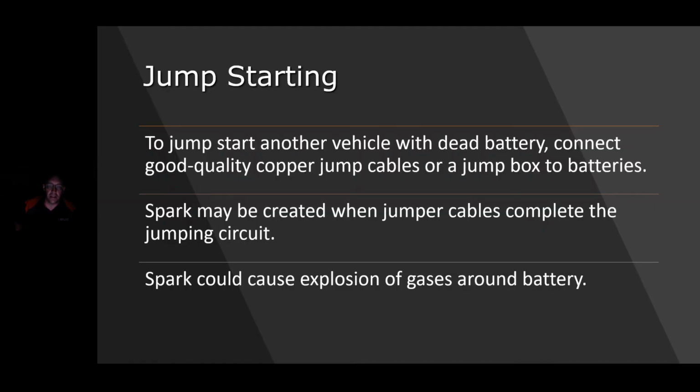All right, jump starting. To jumpstart other batteries, obviously, we need a good set of good quality jumper cables. The spark could cause explosions of gases around the battery, so you want to be careful around that and be careful about causing problems. You know that from Intro Auto. You've been through this.